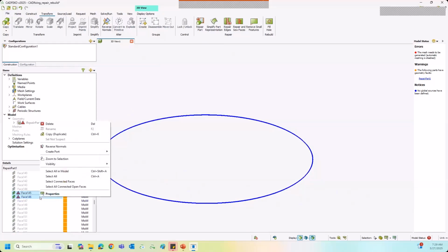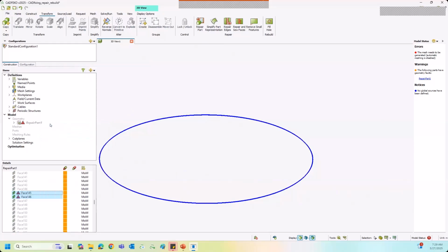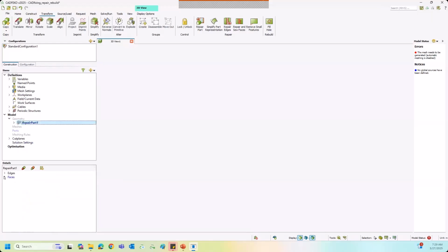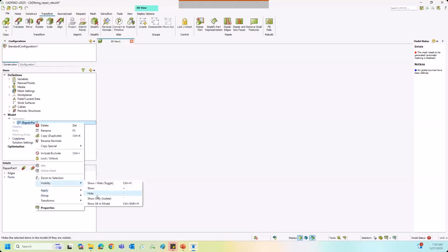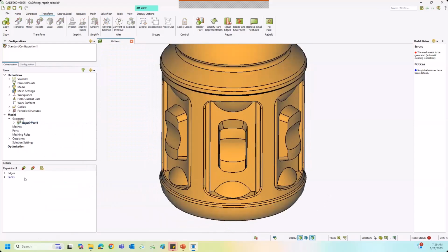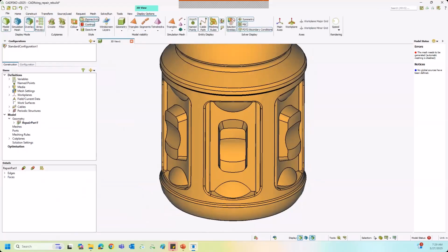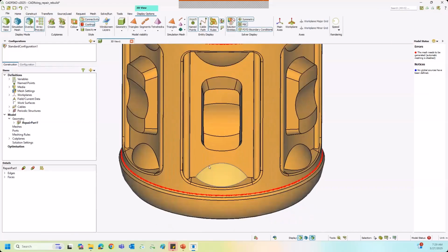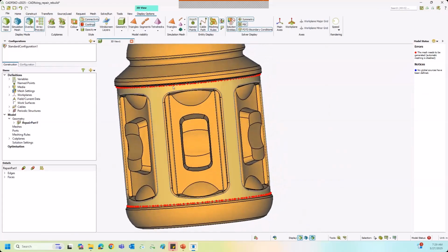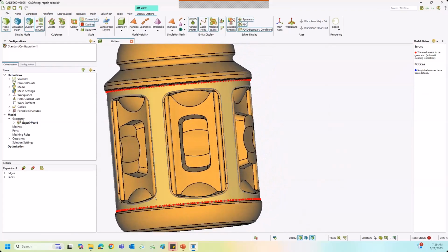So what we will do is try to get rid of them. So I will delete them. But as soon as I delete them, I can see that this particular geometry became open. So there is no region associated with it. If I bring back the whole CAD, show all in the model, I can see the CAD, but there is no region associated with it. And if I go to the display options and enable connectivity, I can see where the openings are. In the two places where I deleted the surfaces, I see the openings.